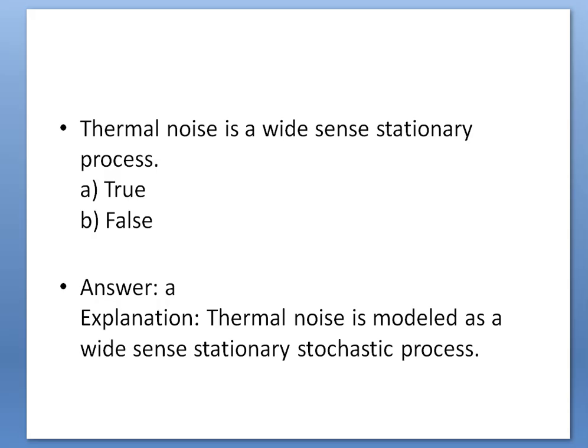So that means thermal noise, the noise added by the temperature either in the antenna or any block in the transmitter or receiver, we have to consider as a wide sense stationary process. That's why thermal noise is modeled as a wide sense stationary stochastic process.